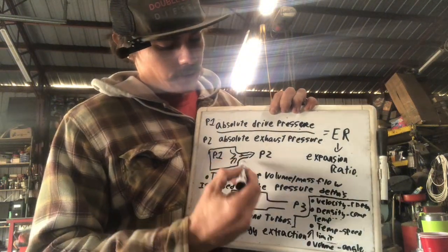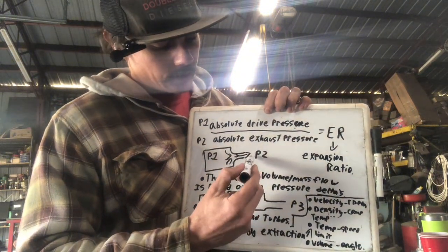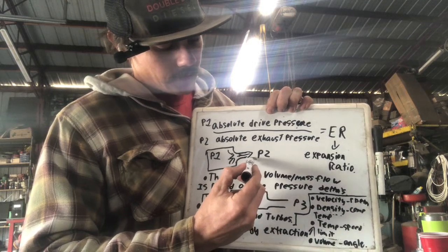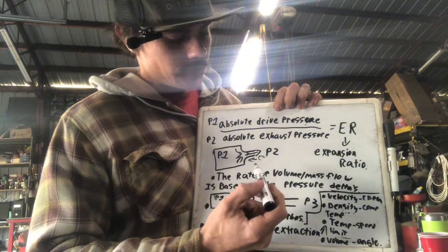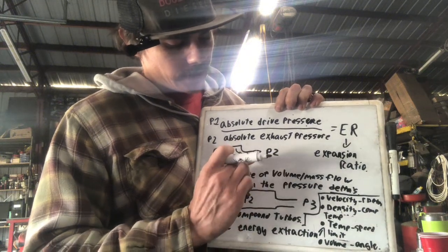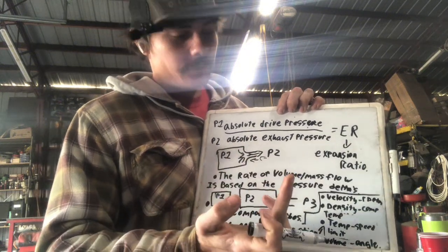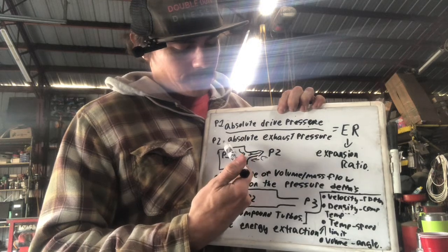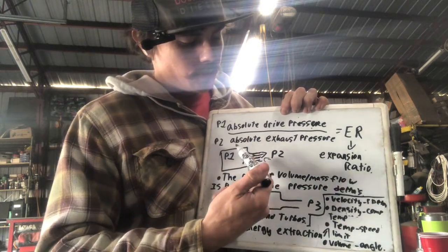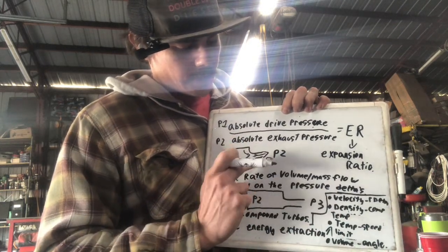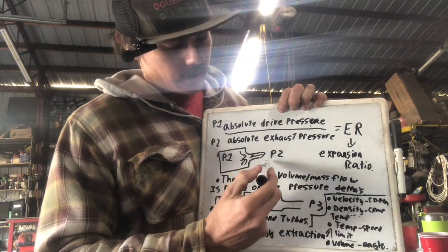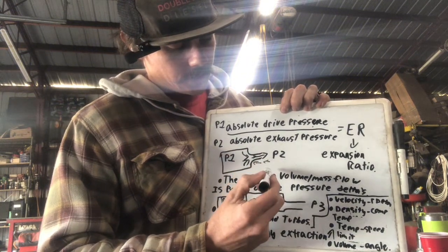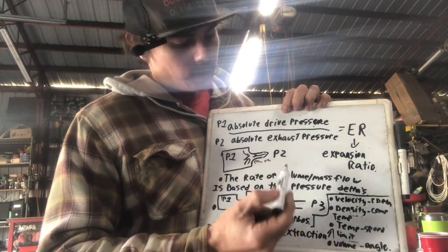When it has reached the local speed of sound, the pressure signal that makes its way up to the feed tank, or exhaust manifold, that tells the feed tank that it can continue to move more, travels at the speed of sound.